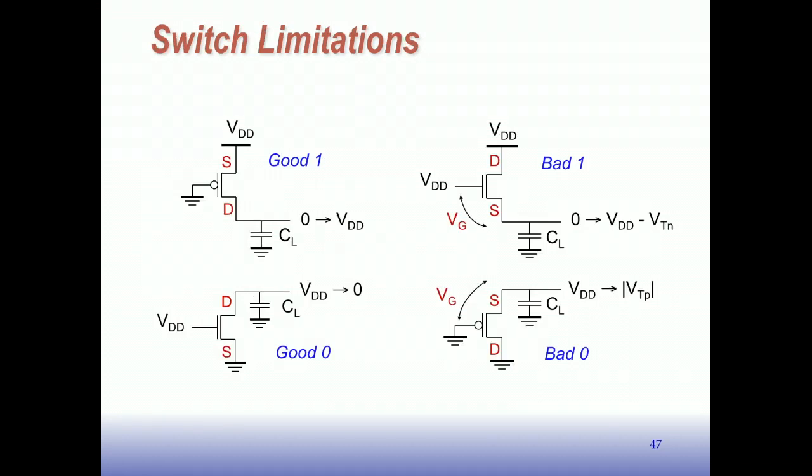So in this configuration, we have a P-type transistor here connecting to some node connected up to VDD. If we put a low voltage on the gate here, this transistor turns on, and this node will get pulled up to VDD. There's some capacitance here, so it takes a little bit of time to discharge the capacitor. Likewise here, for pulling down, we put high voltage here. We have VGS of a big voltage, way past the threshold. The transistor will turn on, and this output voltage will eventually go down to 0 because that node gets connected to ground.